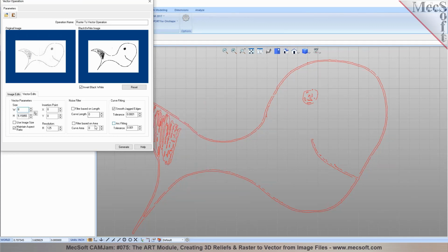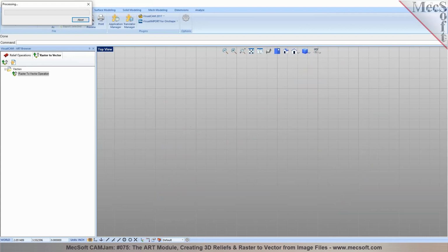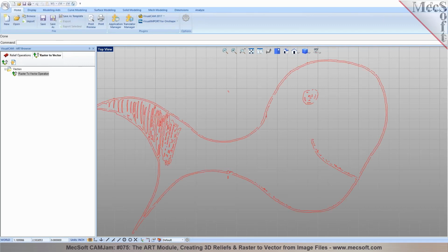And then you can also control or adjust the resolution in here. I can go from 125 to 150. The finer the resolution, you're basically going through more number of sampling points. So consider resolution as being, for every square inch you have 150 squares, right? So that's what the resolution is. If you consider a square inch, you're basically having 150 squares inside the square inch. So that's what the resolution defines.